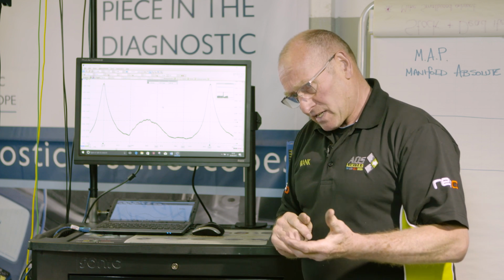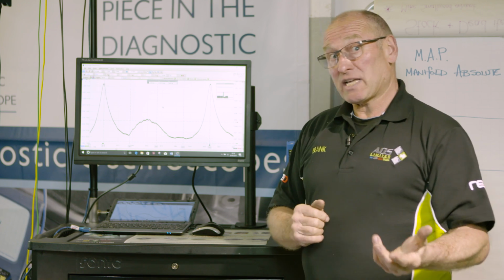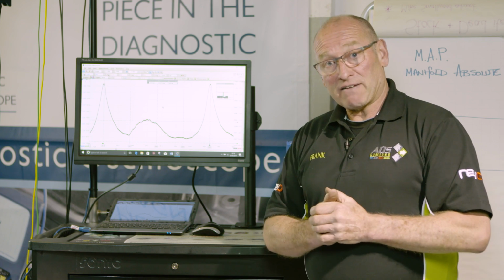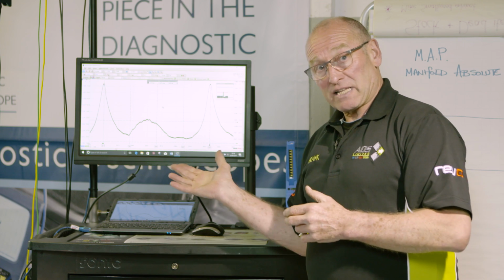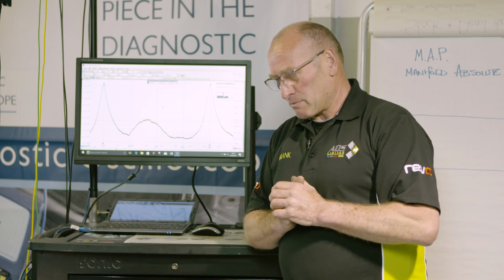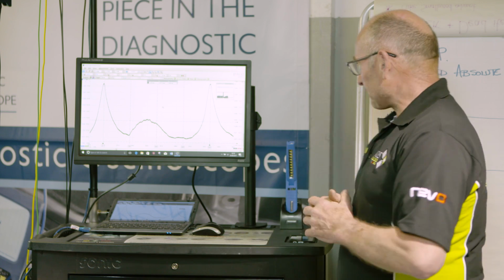How do I know the valve timing is correct? Because I don't really know what the ECU is up to. I need to look at the serial data on the ECU map to understand what the opening position of the inlet valve is electronically, because it's going to affect this evaluation. So you can see I've got this little bit of a conflict here. We're going to do something perhaps that will help us assess that a little bit later on.